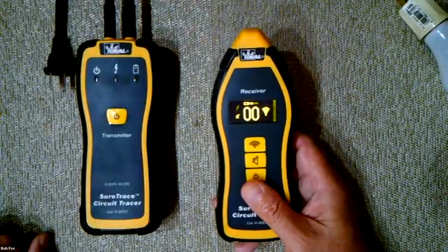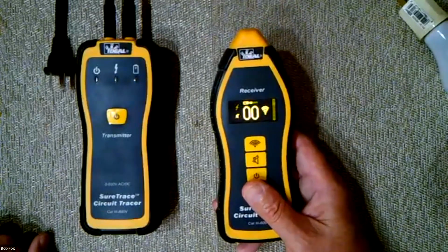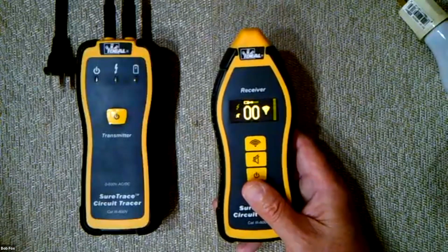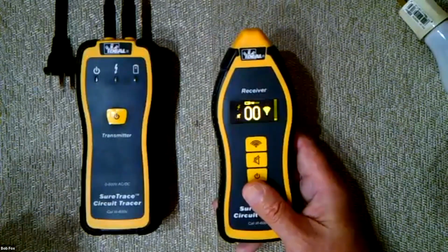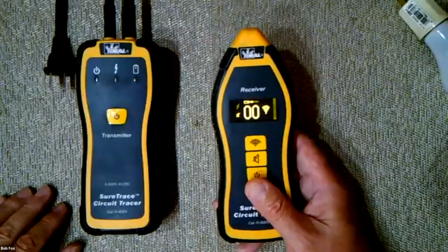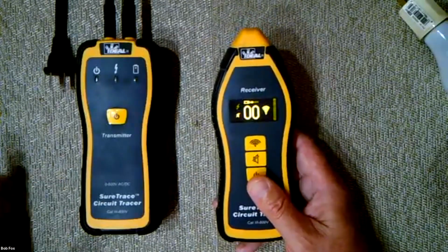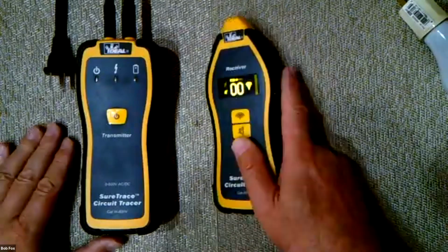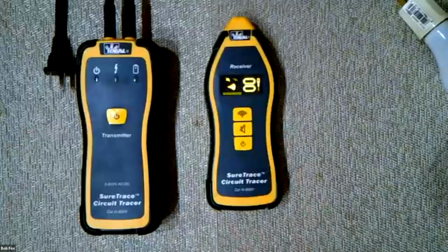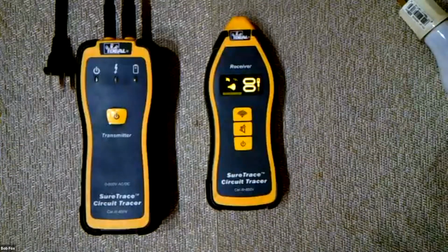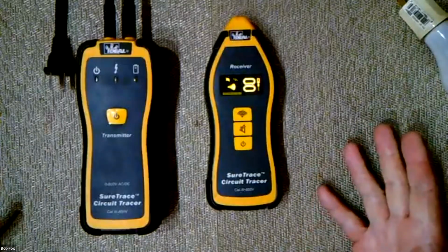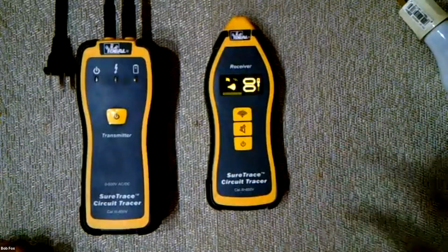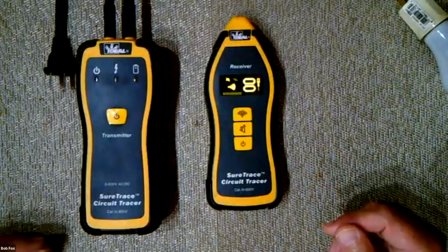Once I've found the area of interest where the problem may be, because don't forget, some runs are 20 feet and some runs are 200 or 300 feet or much longer, that's when I start worrying about getting down on my hands and knees or using the cradle that you discussed. So you don't have to start with a cradle. You can, but I find it interesting that the signal is powerful enough in most cases that you can just walk along and get a good idea of what's going on.